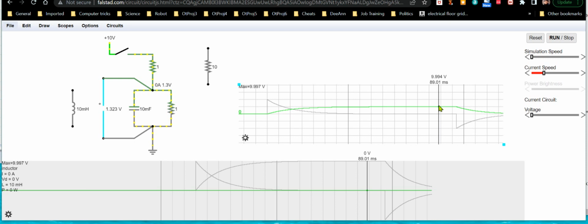Most people have gone through an AC/DC course or whatever. This is like 101 kind of stuff. But I wanted to review it to point out a couple of important concepts about capacitors that will be important later. Namely, when you first apply a voltage to a capacitor, its current is maximum, and it falls off from there.